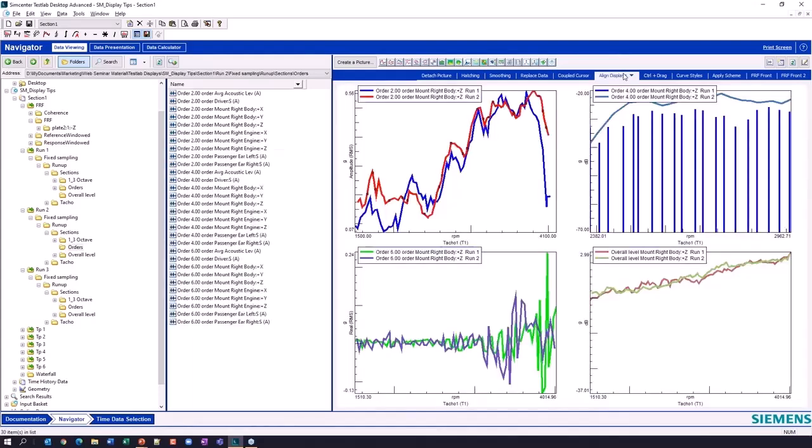To supercharge that, we can use something called align the whole display. So in this case, I've got 4 plots here, and I've got all kinds of stuff that's different. I took extra effort to make it this different in terms of line types and colors and axes and everything else. But I'm going to show you how you can get to one-click, one-stop shop as far as clicks go. So I've got all these displays and they all have different options. I've got amplitude versus real, decibels over here. We've got different x-axes all over the place. This guy is even different in terms of the curve type.